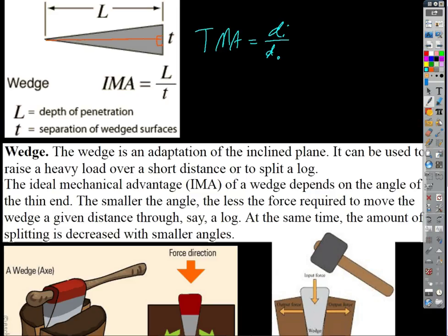You'd want to start a crack in the wood so you could get it starting to split. Now, once you've created a crack and weakened the wood a little bit, what could you do then? Put a bigger one. You could put a thicker, wider wedge in there, and that way with fewer smacks with the sledgehammer, you're going to get this thing to spread apart enough that it'll fracture, right? But initially, when you need to generate these really large forces to bite into the wood, you want to use a pretty thin wedge, don't you?